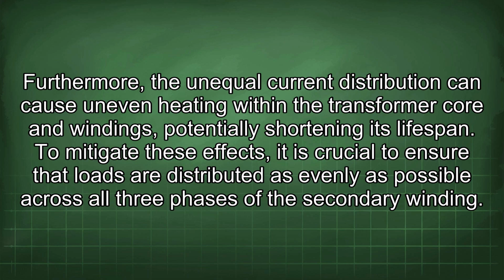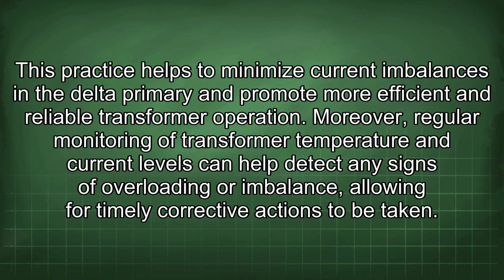To mitigate these effects, it is crucial to ensure that loads are distributed as evenly as possible across all three phases of the secondary winding. This practice helps to minimize current imbalances in the delta primary and promote more efficient and reliable transformer operation.